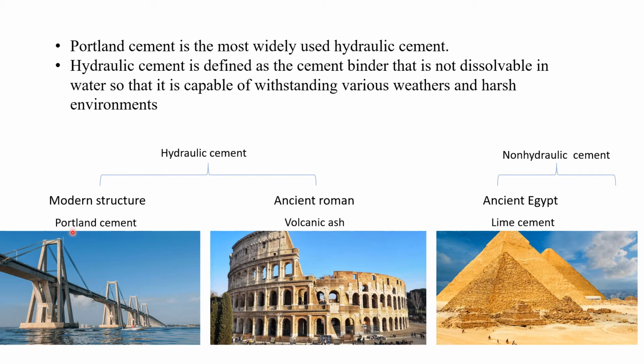So Portland cement solves this problem. It can be mass-produced almost anywhere in the world. Another advantage of Portland cement is that it can gain strength much quicker than volcanic ash cement. Typically, it takes about 7 days to get sufficient strength for testing, but for volcanic ash cement, it usually takes several months.